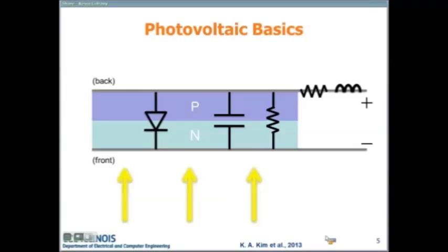If you take a power electronics or any modeling class, you're going to have some series resistance and some inductance, because it's actually a wire. So these are the series resistance and series inductance. They can't be completely left out. This is if it's just a hunk of a PN junction sitting there, but it also works as a photovoltaic source, right? So you have to model the sunlight coming in to the panel, and we did that using this source called a photocurrent.